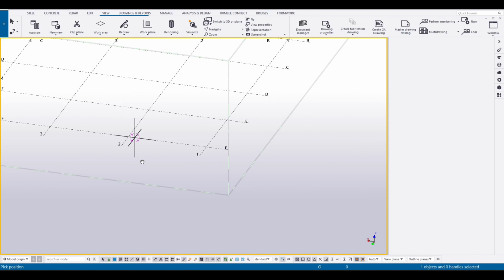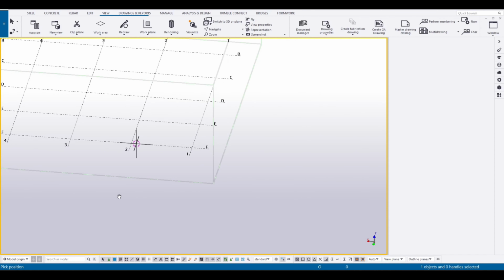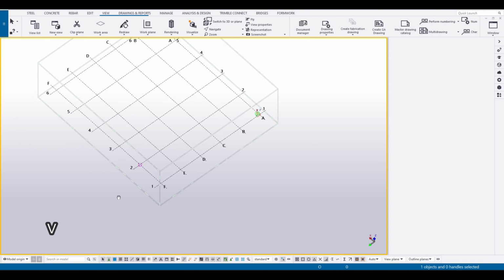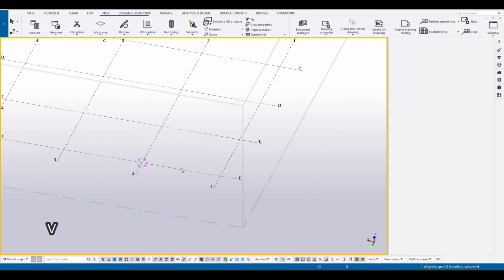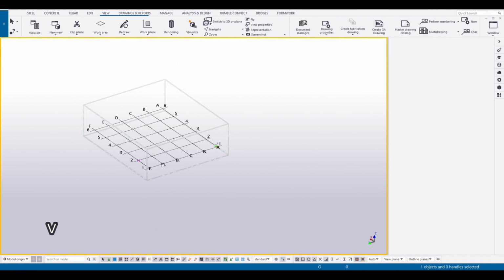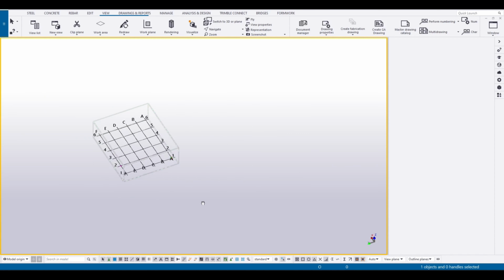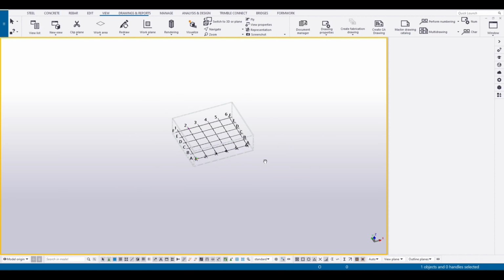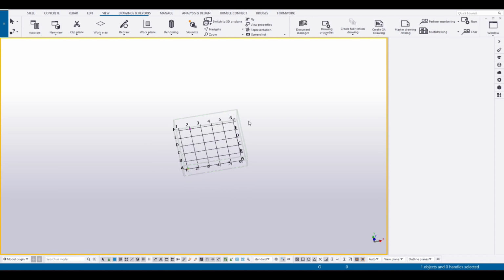And the other way to change the rotation center point will be by hitting V. Once you click on V, you can also find the intersection of the point that is right there. Here is the rotation center point. Great. So now what do we know in Tekla Structures? We already know how to move, how to zoom in, how to zoom out, how to rotate, basically the basics of Tekla Structures. Now what we want is to open the plan view.